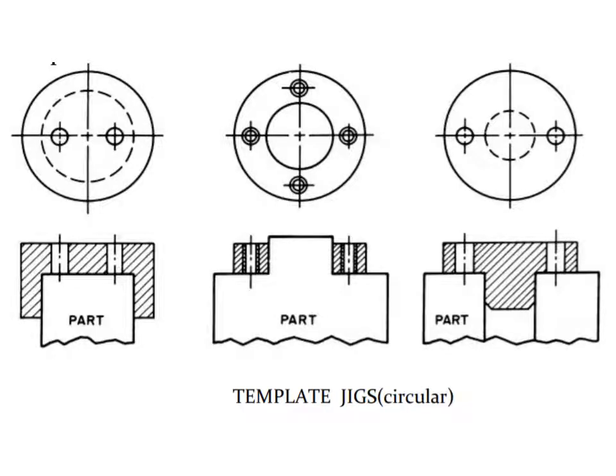So this is a time consuming and laborious process, and not only that, if you want to repeat this for more than one component, the skill of the operator or the person who is doing the marking onto the disc is very important, because the dimensions can vary from component to component according to the way the operator is taking the dimensions, because every time he is marking the center of the disc by trial and error.